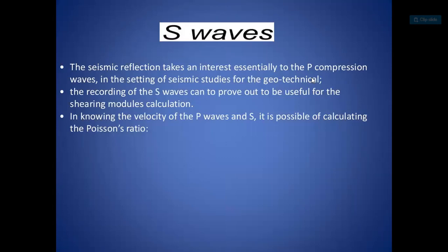Seismic reflection is essentially interested in P compression waves in the setting of seismic studies for geotechnical purposes. The recording of S waves can be useful for the shear modulus calculation. Knowing the velocity of the P waves and S waves, it is possible to calculate the Poisson's ratio.